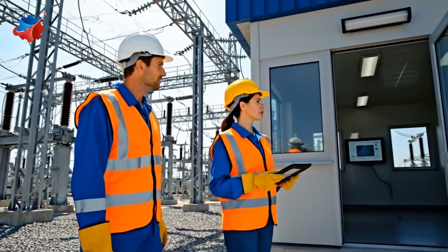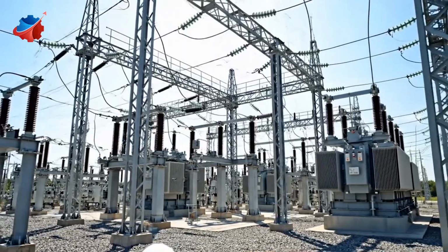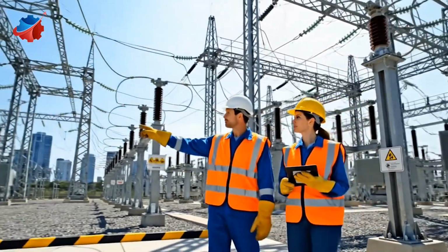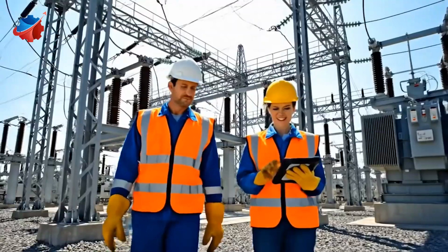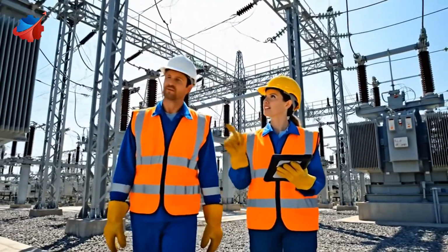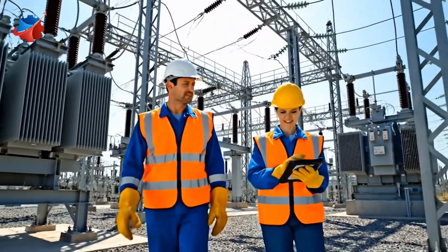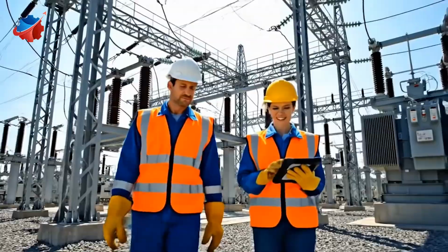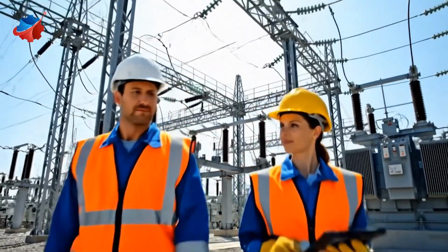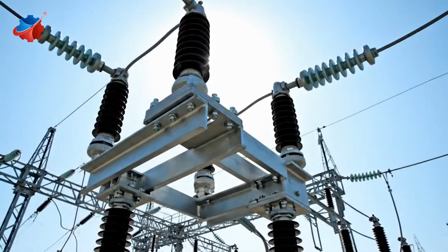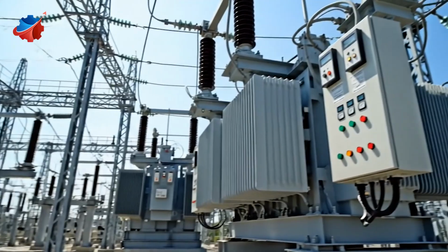Yes, let's move inside to the control room and initiate it. Confirmed. I'm noting the visual inspection results on the tablet now. This reading confirms the clearance issue on the south transformer bank. Agreed. And visually, the alignment on these insulators looks stable for now. Ensure all connections on the bus bars are torqued correctly. I've double-checked the readings. Everything looks secure.